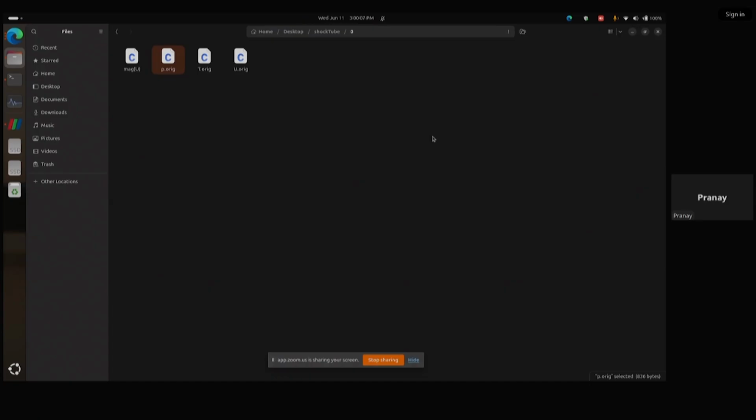Basically, these orig files are used to maintain or preserve the original structure. Once we move on to the case ahead, you will see we are generating the P, T, U files using a different methodology. And magU represents the magnitude of U, or the absolute velocity, which is the square root of ux squared plus uy squared plus uz squared.